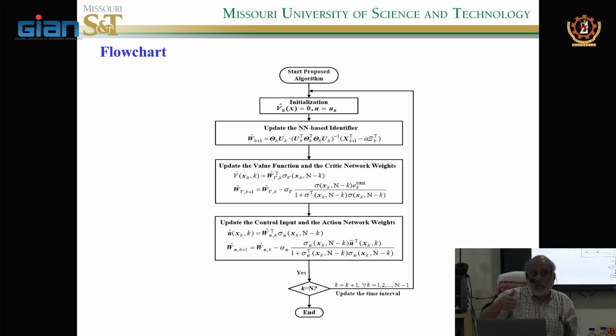So a lot of times control methods do not consider the actuator limits. So what happens is the control signals are very large sometimes, if you don't choose your gains properly. But the actuator has limits. So sometimes it saturates, you have the same problem. So I'm going to show you as part of this how we can use the actuator saturation as part of the optimization. Okay? Any questions here?